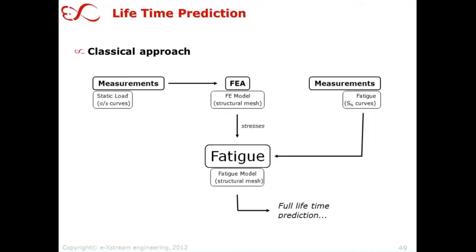And these stresses, which are computed, go as a stress field into some lifetime prediction fatigue software. And this software then relies on the SN curves to predict then the lifetime of the part. So all this is fairly easy. Well, it's not easy, but it's straightforward and available in a workflow. If you go for isotropic material models basically behind. If you then want to go for short fiber reinforced plastics, as we have seen in all the presentation, it's anisotropic. So what changes in this approach if you move to anisotropic?